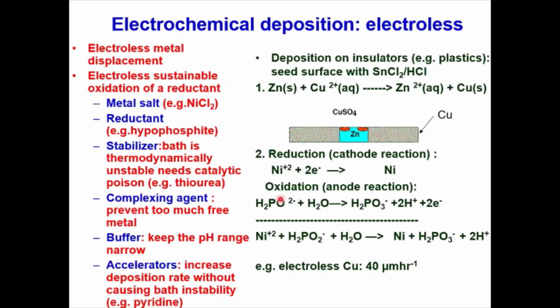All right. So the process is that you take the reactants, all right, just insert the electrode, whatever electrode you want, put in, the deposits take place. For example, if you want to have nickel deposits, right, you have nickel chloride, hypophosphite, a stabilizer, complexing agent, and an accelerator in the solution as electrolyte, and then nickel gets deposited onto whatever electrode you have as connecting medium. So this is electroless deposition. You didn't supply any electric current or potential, right? Just with the electrolysis within the salt, right? The metal gets deposited, right?